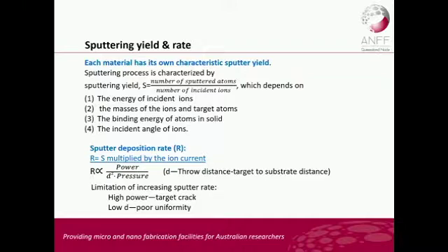But there are some limitations to increasing the sputtering rate. You can have a higher power, but higher power may crack your target. And if you reduce the distance from target to substrate, it may affect your uniformity.